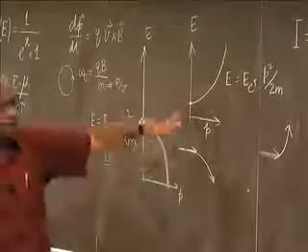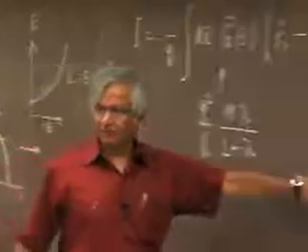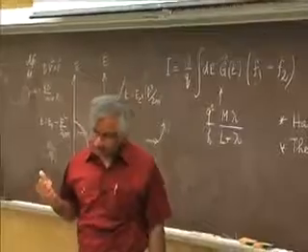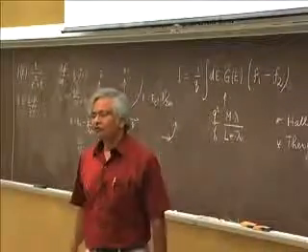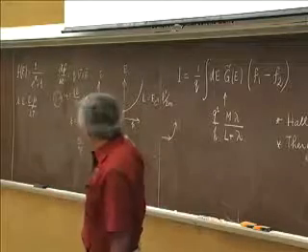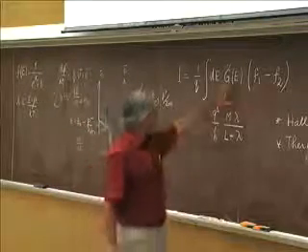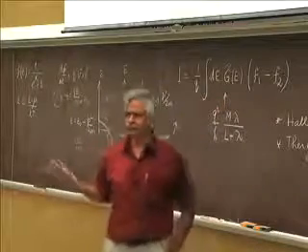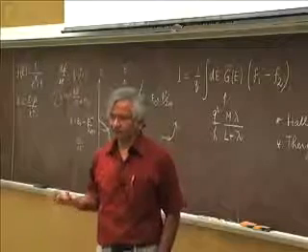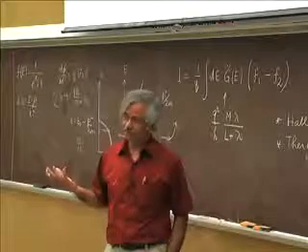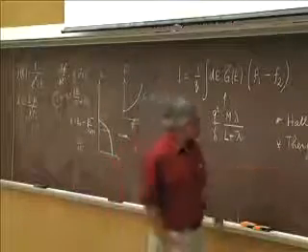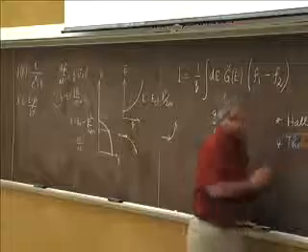But when you talk about the thermoelectric effect, which is what we are discussing, there is no real difference between the two bands anyway. And one interesting point, as a result, which I feel is related to this: when you look at amorphous semiconductors, I made the point that a lot of what we are talking about in terms of density of states is applicable even if you don't have an E-k relation. Even if you are talking about anything small where you don't really have an E-k relation, or an amorphous material. When you go to amorphous semiconductors, they still measure a thermoelectric effect that is quite well understood.